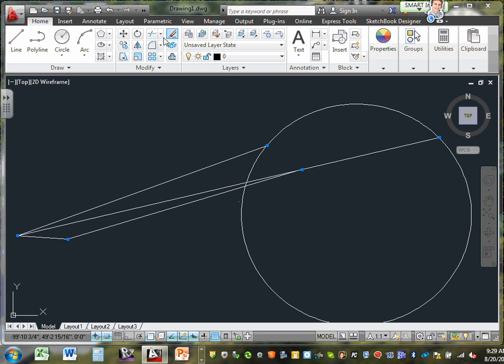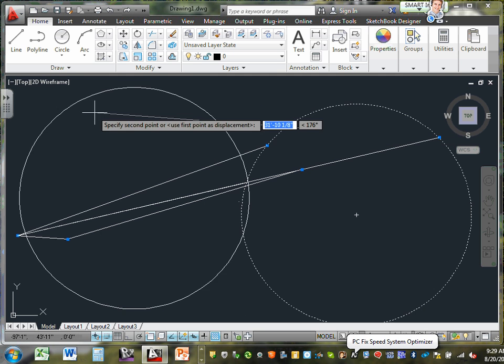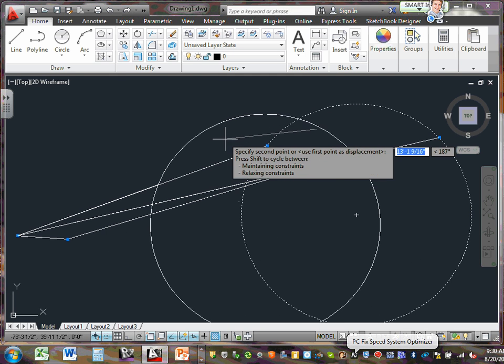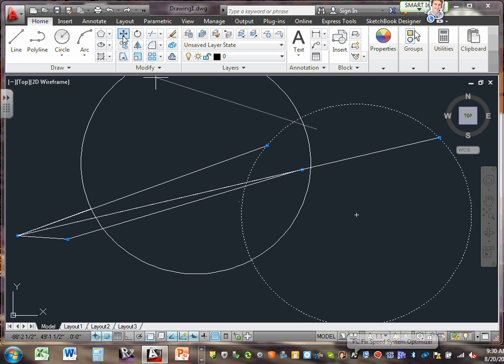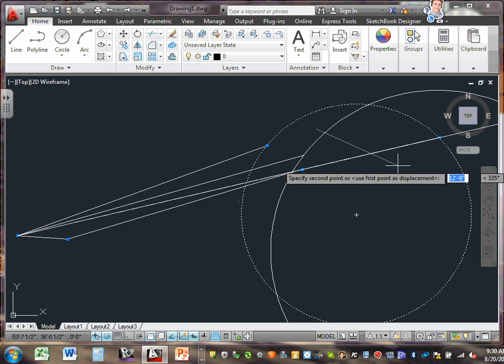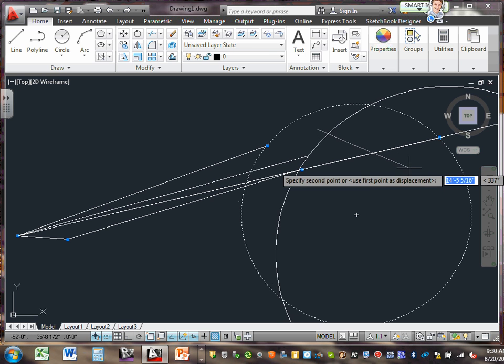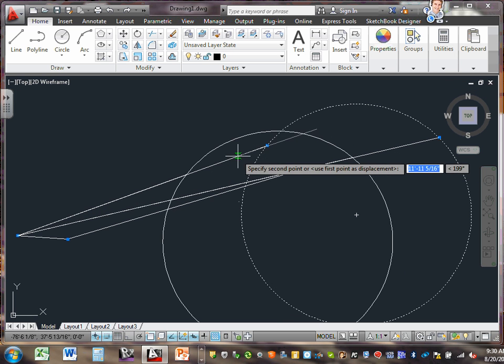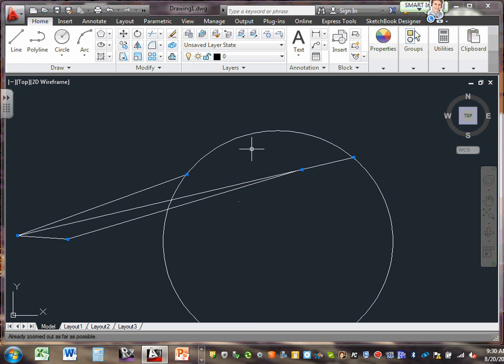So moving, guys, you pick the function, move, then you click on the object that you want to move, then you right click, then you left click and you move the object. Did you guys hear me? First click on move, then click on the things that you need to move, then right click, then left click and start moving. How many clicks? Can you guys please practice moving? Please take anything you want to move. Doesn't matter. I want you to know click and move.